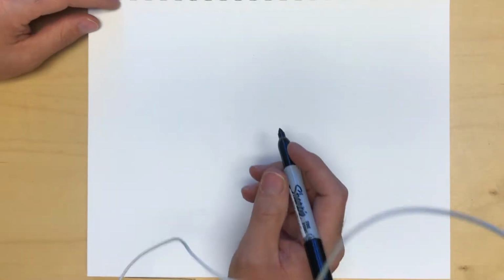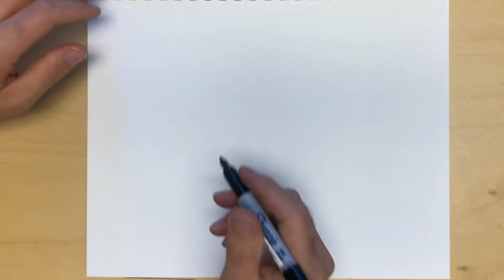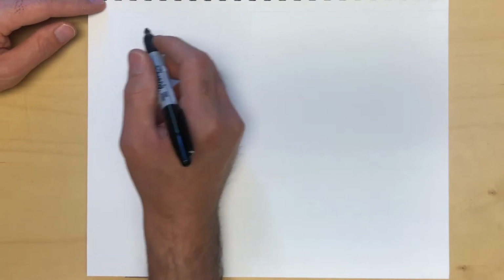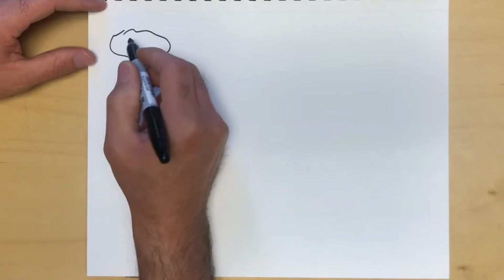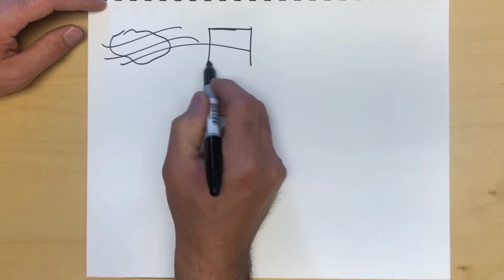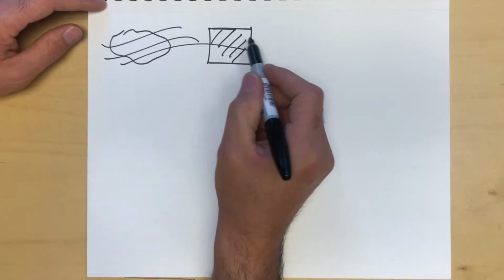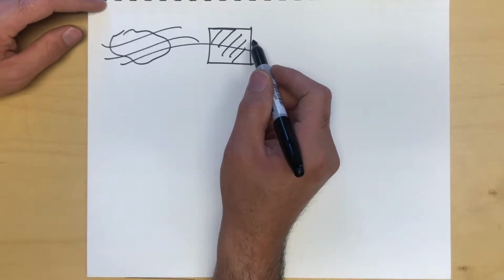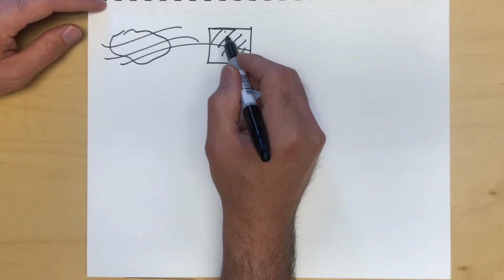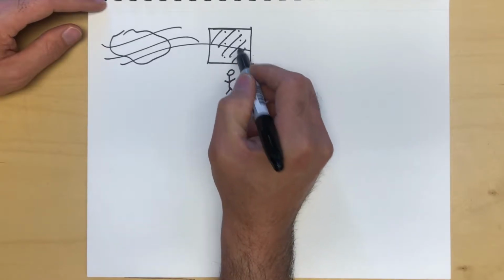Okay, the next step in our analysis is to do the differential form of the continuity equation. And remember, last time we derived the Reynolds Transport Theorem, which allowed us to move from a system perspective to a control volume perspective, where we preferred the control volume formulation because it allows us to have this Eulerian frame of reference where we can assign velocities and properties at a point.